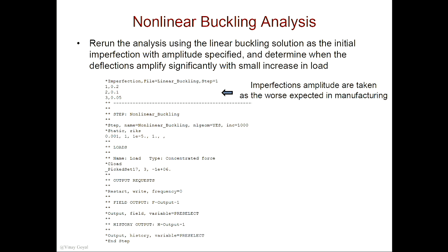If you have the scan, if you know exactly what the imperfections are, if you know the thicknesses of the structure, you can use that information directly and move the nodes yourself. You know, take the cylinder model, write a code that moves these nodes in a way that includes that imperfection. You follow me? You follow what we're trying to do here? If I know there's a dent, somebody dented the cylinder, well, I could model that dent. I can make it dented on purpose and then run this analysis.